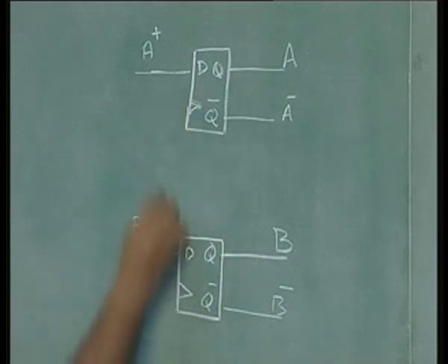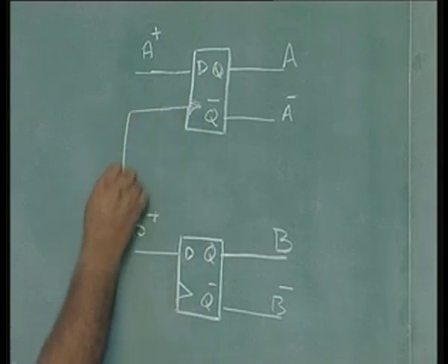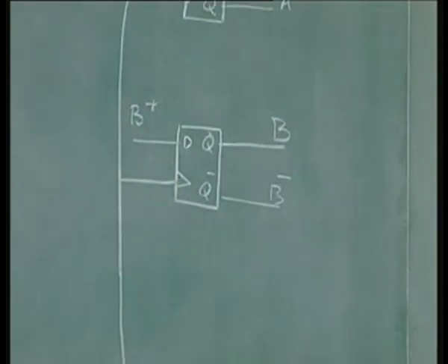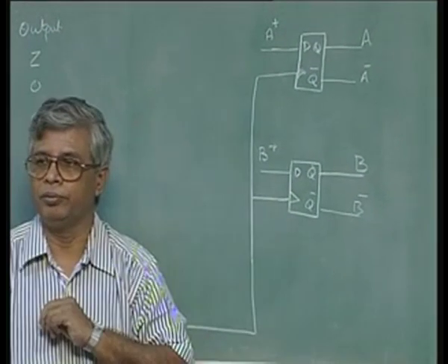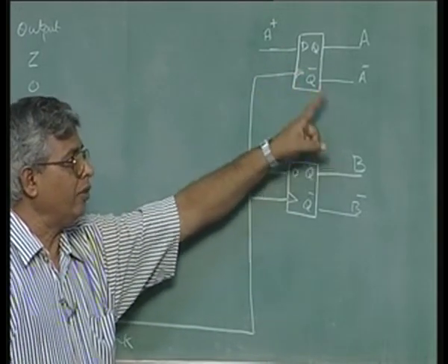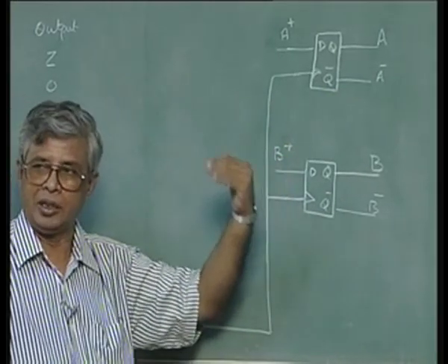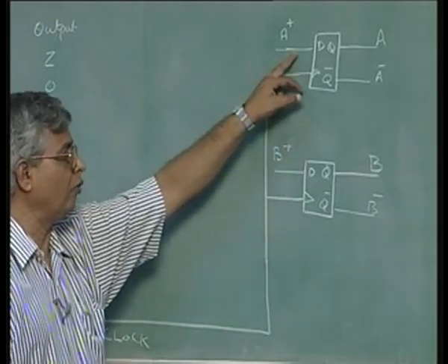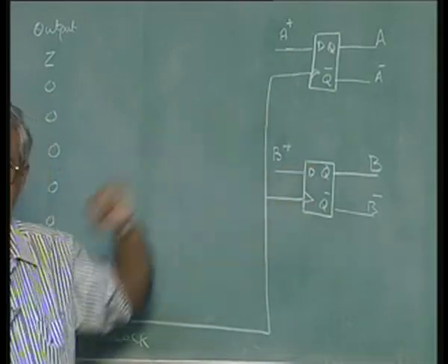This is required for the 4 states. For 4 states, we need this type of 2 flip flops working. Now, the question is, the 4 values of A and B, 0 0, 0 1, 1 0, 1 1, will occur based on the present state and the input given. That information has to be given to these inputs of this flip flop, DA and DB. Only then they will change state accordingly.